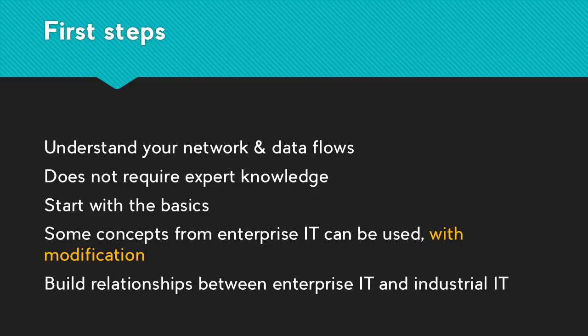I'm very big on doing a data flow analysis. Now, to OT folks, to ICS folks, a data flow analysis is extremely detailed. They're talking about, I'm sending you 20 milliamps at 5 volts for 2 seconds from this valve to this meter. We don't really need that level of detail, but we do need to know that that meter is Ethernet connected.